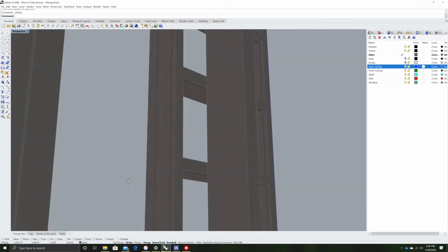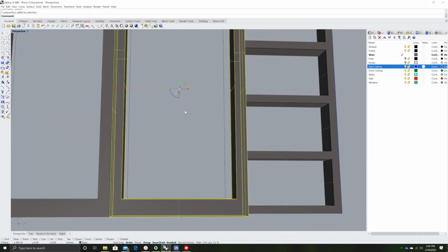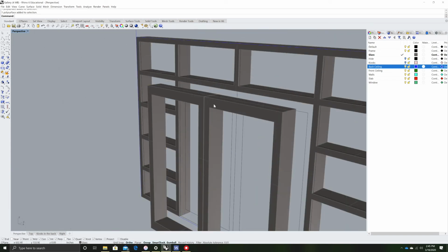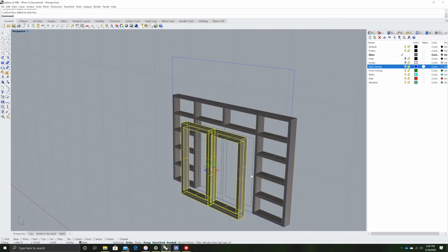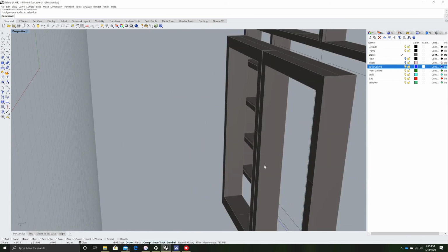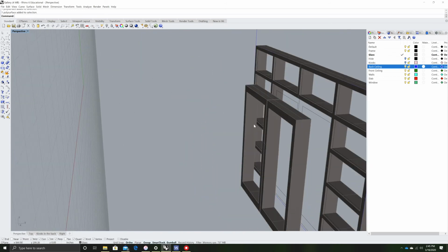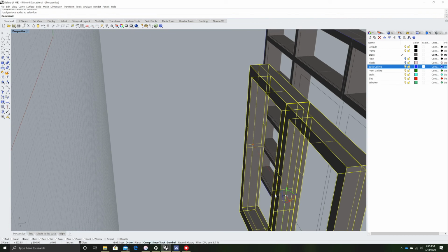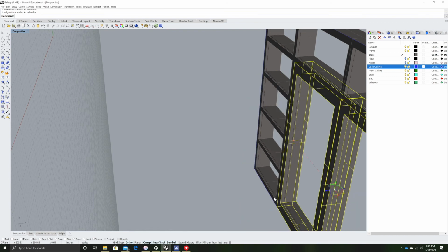And then delete that extra section there. Okay, so now we should have those doors separate. So the next step is to make them a little bit thinner. But actually, let's hold off on that. Let's do that after we finish our glass up. So let me just move them back into position. We moved them out 24, so now we're going to use this blue little arrow here and go -24 to move them back.